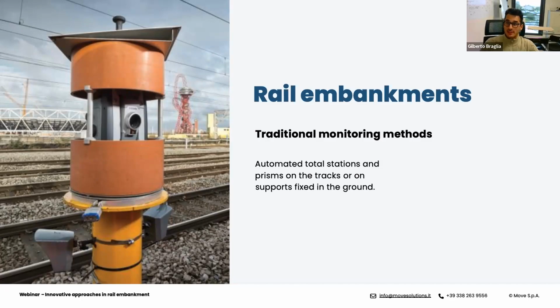It's basically an instrument that is placed on a spot that is assumed to be still, and with some targets, you can measure several points, in this case on the railway or along the embankment, to see how all these points move with respect to the point of installation of the total station itself.